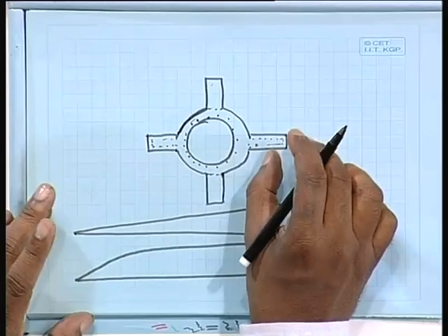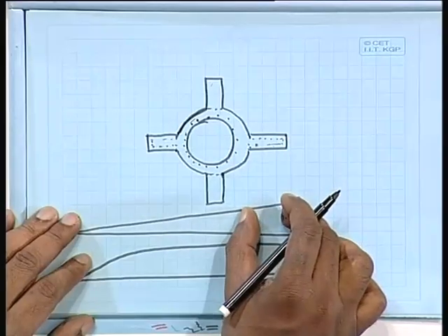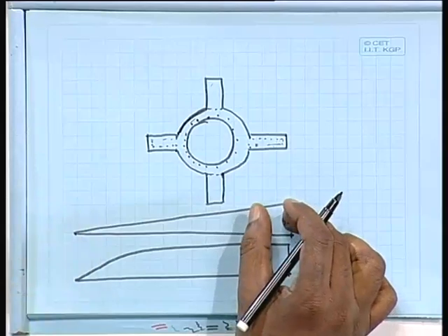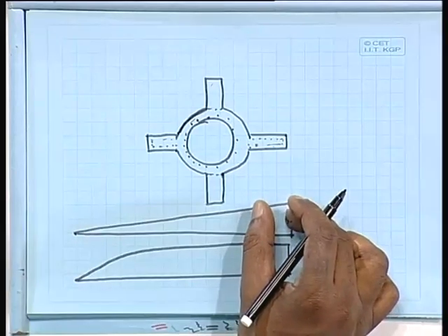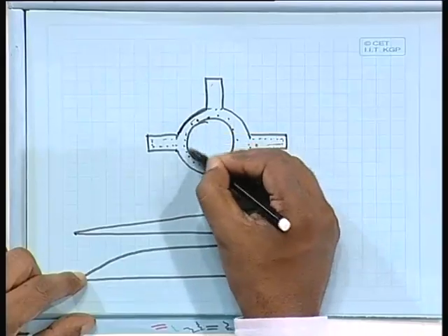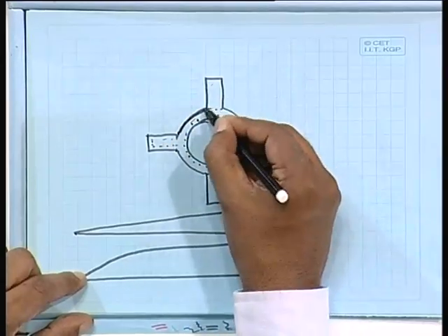rectangular and circular shapes. For a rectangle placed here, you find out the strain diagram and the stress diagram, and you individually compute the moment capacity and the axial load capacity. For this section you find out, for that section you find out and subtract it, and similarly for this one also.